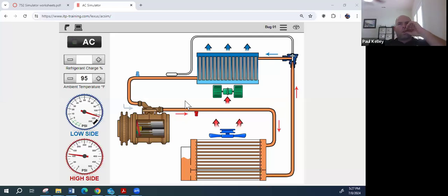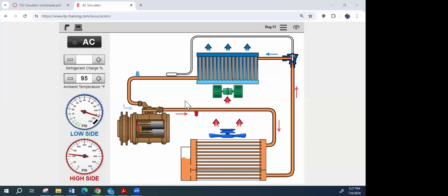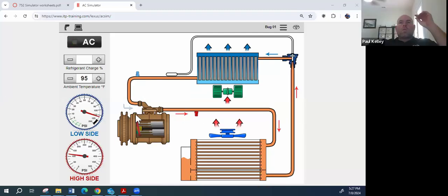Anything that's a little more to the point, right? Because you want to eliminate a lot of things in one swoop. You can check the relay, I agree. You can check the fuse, I agree. But you could check something that would have checked both of those. We can test the compressor if it's getting voltage and ground, so power and ground. Okay, right at the compressor. That kind of makes sense to me. You could go ahead and do that.